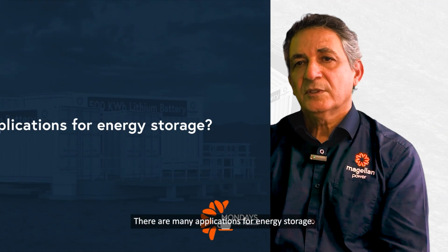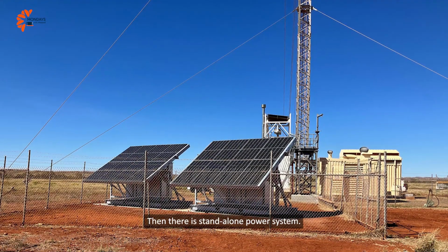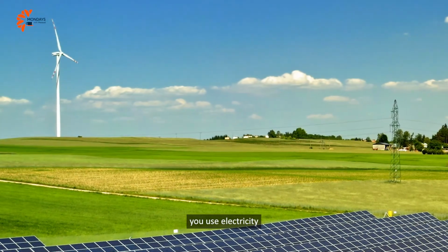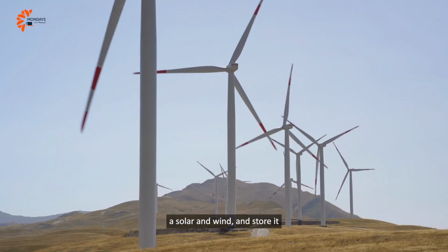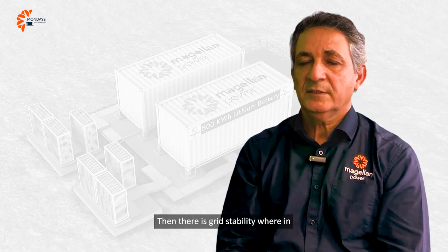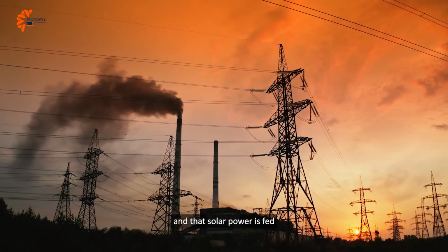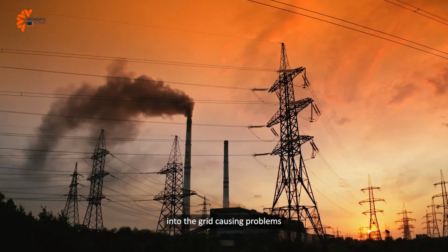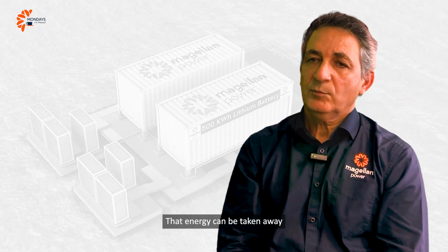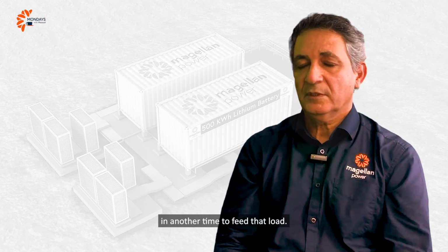There are many applications for energy storage. The obvious one is uninterruptible power supply. And then there is standalone power system. In a remote area, you use electricity, solar and wind, and store it and then use it when they're not available. Then there is grid stability, where there is a lot of solar, and that solar power is fed into the grid, causing problems, and that causes instability for the grid. That energy can be taken away from the grid and stored and used at another time to feed the load.